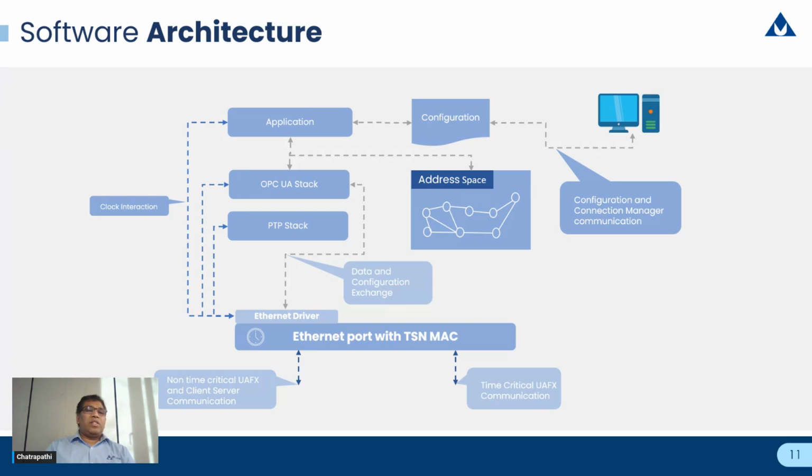This gives the configuration data, and the controller application itself, which sits on top of an OPC UA stack, and there could be other PTP related stacks that execute the time synchronization routines, and then the address space itself based on the OPC UA FX information model, and then any companion specific information model which are standardized for domain specific applications.